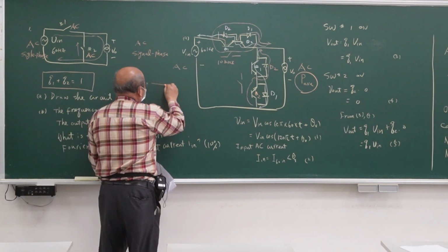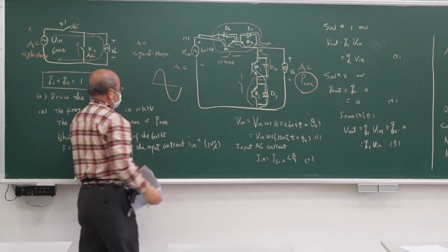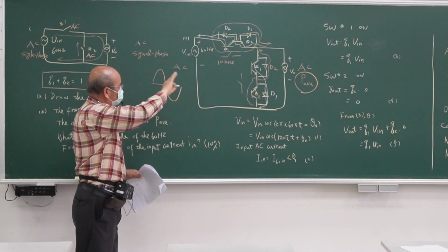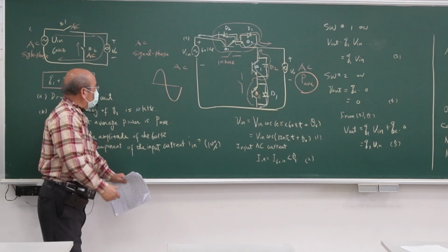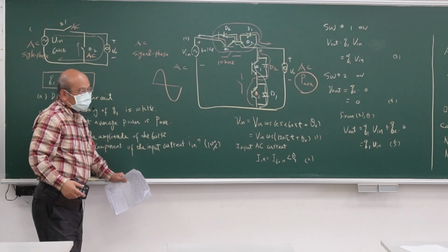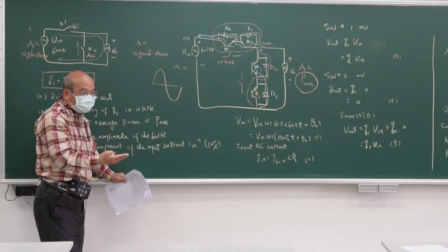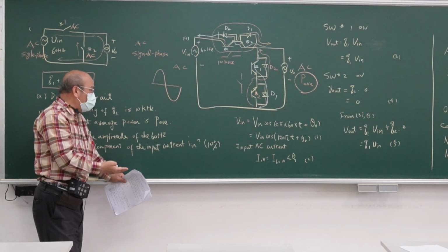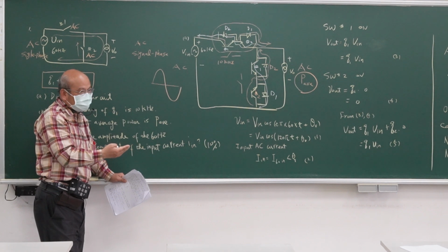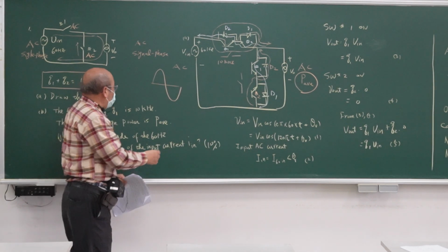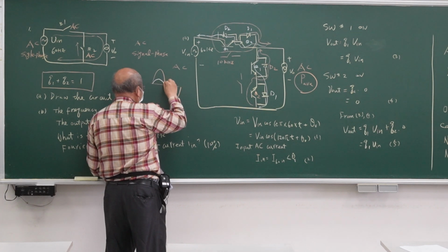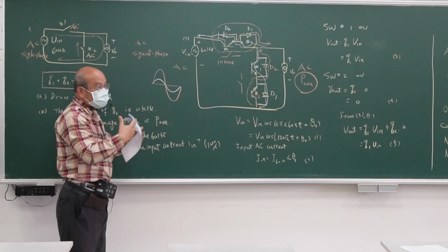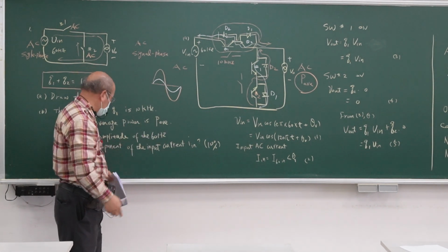So here we have a voltage like this, and now we want to transfer energy to the output. We don't know the real current, but the real current has a fundamental and harmonics, right? If you want to transfer power, what is the most important? The fundamental. So we hope the current could be like this. The other parts are harmonics, but the harmonics are so small that we just neglect them.